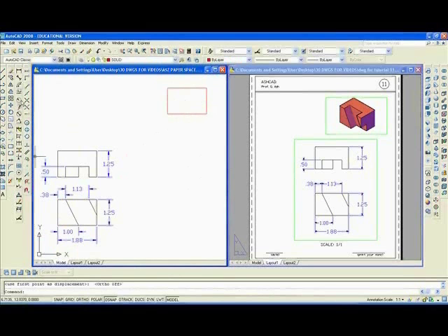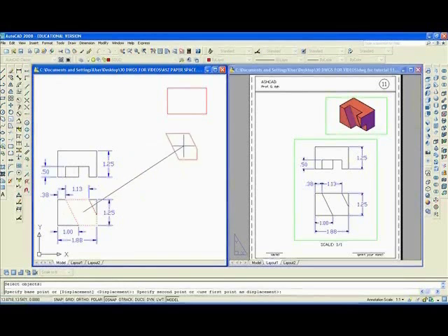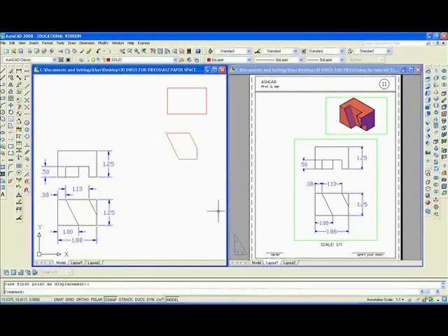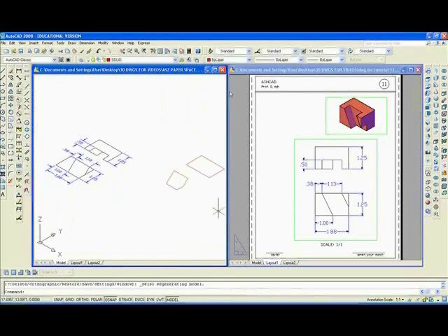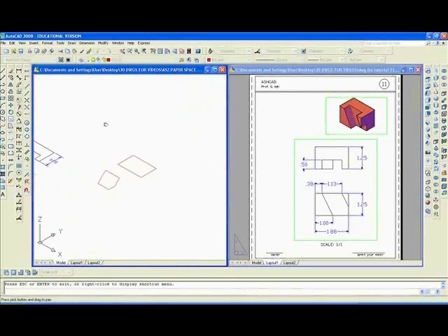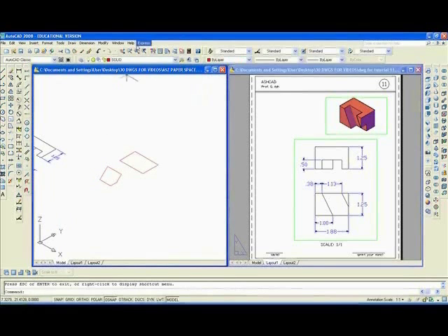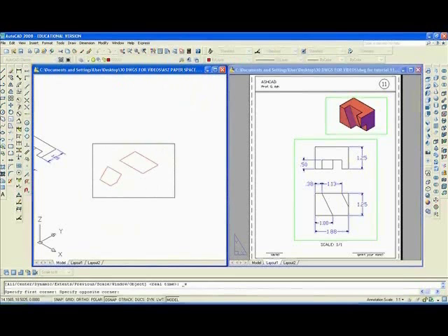Now I'll go and use a polyline and trace over this thing, I don't know what you call it, C to close, and I'm going to move, L, enter, move the last thing I made from here out to here, and then we'll go into southeast isometric, and we'll pan and zoom so it's enlarged, what we're going to make into a solid.